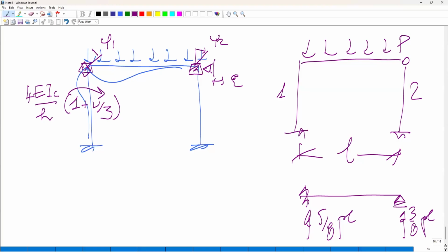This is an exercise that you probably solved in your structural mechanics class as one of the first exercises. So solving these exercises, doing these hand examples, also helps you in understanding how to distribute the loading. And also, if you have to pre-design your structure before you go for any computer model, this is what you do. You say, okay, this is 5 alpha and 3 alpha. Let me give the columns these sizes here. So there is this step.